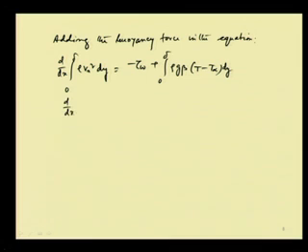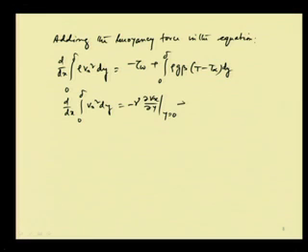So, if rho is constant, we can write d dx of integral Vx square dy is equal to minus tau w by rho plus the buoyancy term. Tau w is equal to mu into del Vx by del y at y equal to 0, so we write nu into minus del Vx by del y at y equal to 0, and plus integral 0 to delta g beta (T minus T infinity) dy, since rho cancels. So, this is the situation.